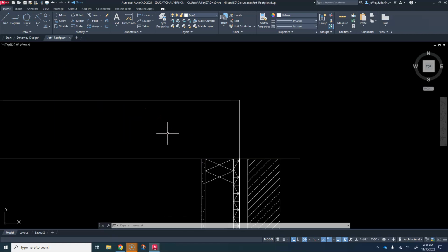And we have to determine our roof pitch. This is where things might get a little bit confusing. You remember in math class, I hope you paid attention that day, when we talked about slopes. We're going to use a slope here, and we have different ways of measuring our slopes. I'm not sure if you did it this way in math class, but out on the job site and in the construction industry, we base our slopes off of a standard 12-inch segment, a horizontal 12-inch travel, if you want to call it that.